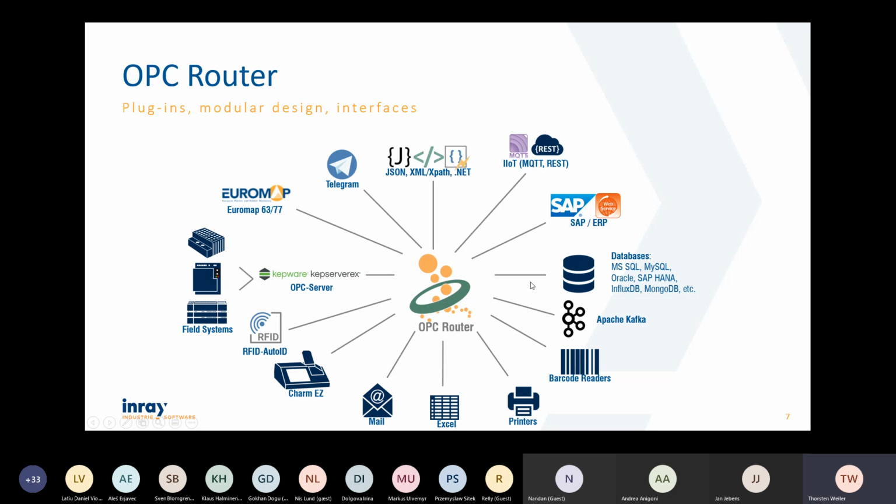But what you can also do, because of the availability and the high amount of plugins, is connect your PLC with your ERP system, and get a new production order automatically transferred to the PLC as soon as the previous production order has been finished. The PLC can give a handshake back to the ERP system, telling it that the data has been successfully transferred and that the production now starts.